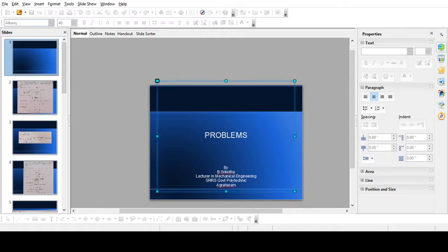It is simply E is equal to 2C into (1 plus 1/m). So 1 into 10 to the power of 5 is equal to 2C into (1 plus 0.25). So the C value is simply 1 into 10 to the power of 5 by 2 into 1.25. So you will get the C value as 0.4 into 10 to the power of 5 Newton per mm square.